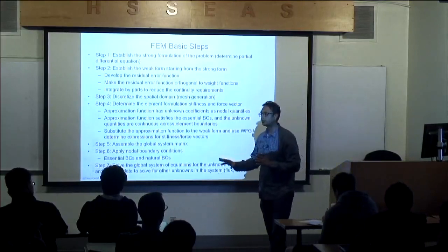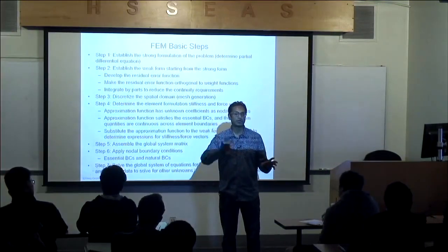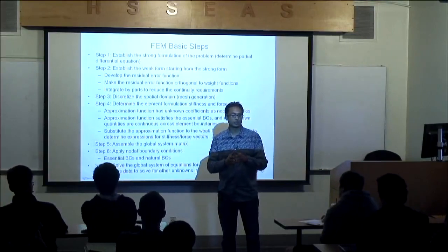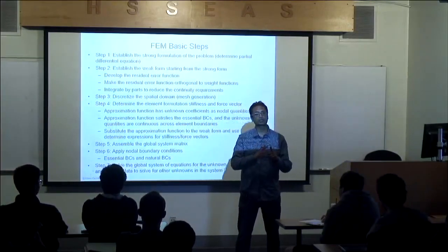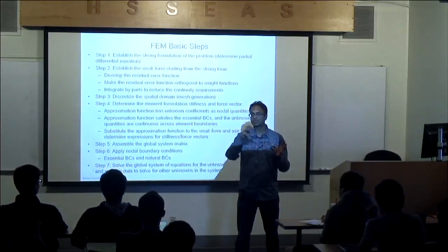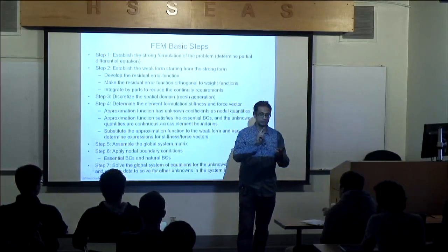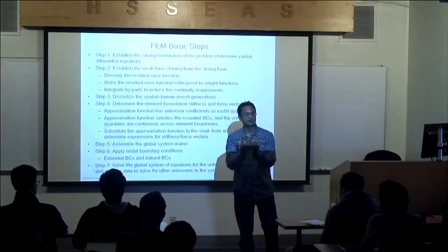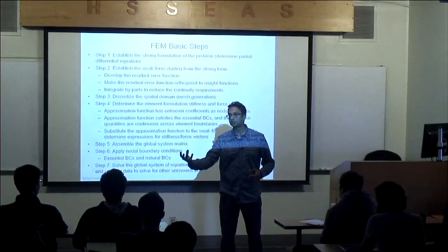We found that when we formulate the element, it's very painful to calculate all the shape functions for every single element, and the integration over an element can be complicated. So why not just come up with an approach where everything gets mapped to either a square or a regular triangle or a shape that is standard. I calculate everything in that standard geometry, and that helps because the shape functions are the same, the integration scheme is the same, the derivatives of these shape functions are the same for every element. And what I've done is I've decoupled the geometry from the problem, and I track the geometry using the Jacobian. Is that clear?